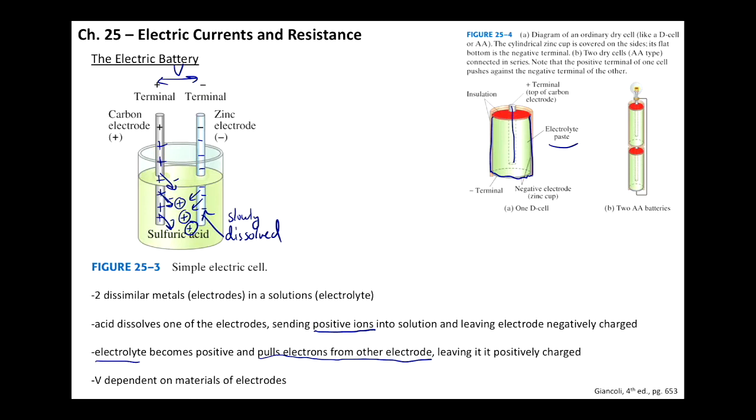I researched thermoelectric materials, which in a way is kind of like this semester in a nutshell, right? Electric. Thermoelectric materials, it turns out, are materials that when you make a temperature gradient across them, make one side hot, the other side cold, they generate a voltage, which is kind of cool. And vice versa. If you force them to have a potential difference, one end gets hot and the other end gets cold, which is kind of nice. People were interested in trying to use it in refrigeration and air conditioning technologies because it's solid state and it would be better than having to deal with various gases and things that are being transferred. But alas, the efficiencies are very, very low. And I don't think anyone has cracked that nut yet.